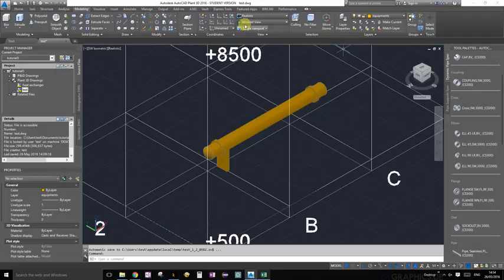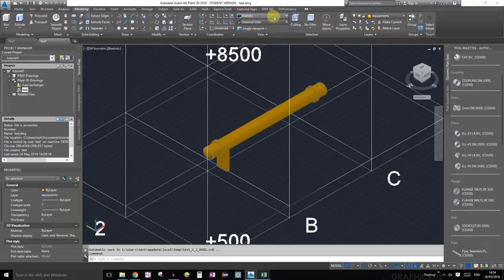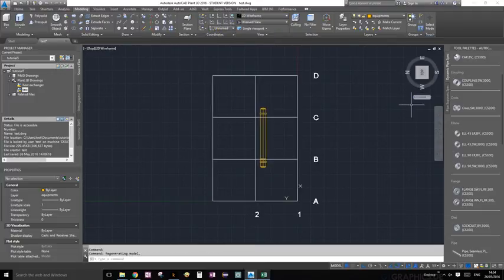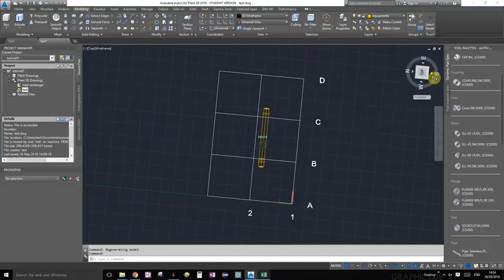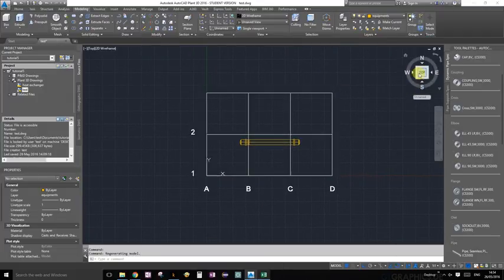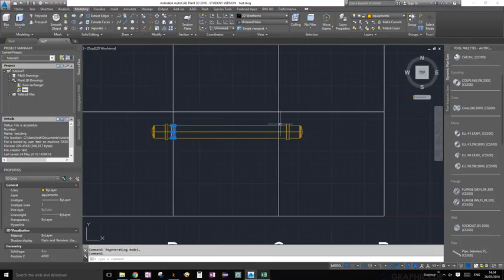Okay, so let's switch back to our 2D wireframe. We're going to click on Modeling or Home again, and under the View palette we're going to click back to 2D Wireframe and go back to the top view again. Here, the top view kind of works. You can work in whichever way you want, it doesn't matter, but I like the other view. So I'm going to click and drag this little wheel here, get it almost all the way to the view, and then click on Top again, and then it kind of levels up, which is nice.